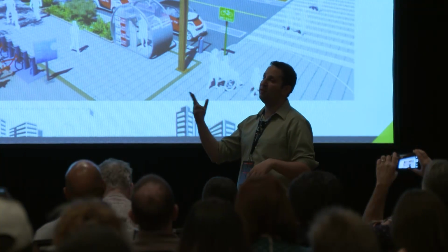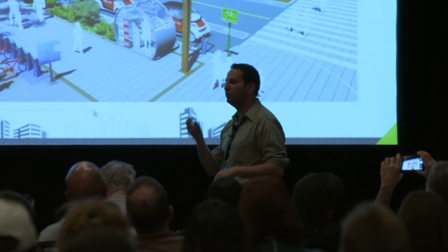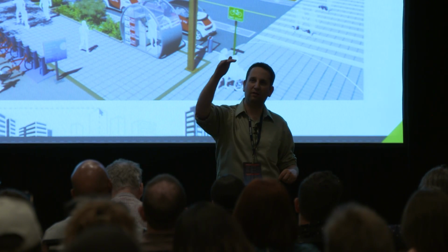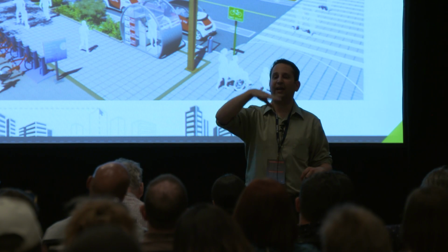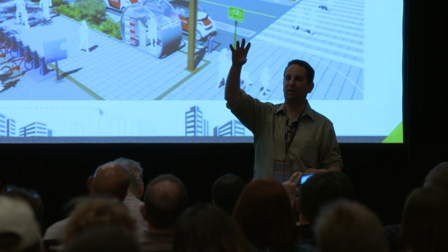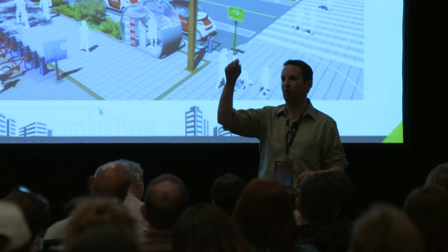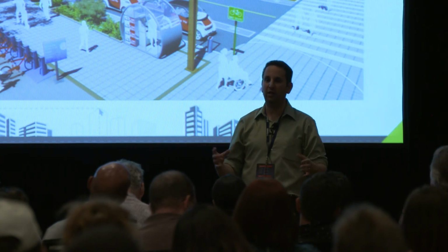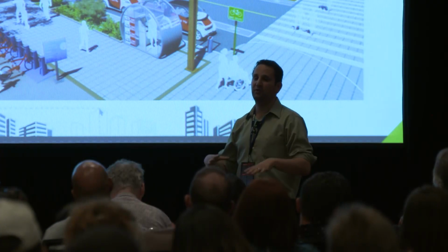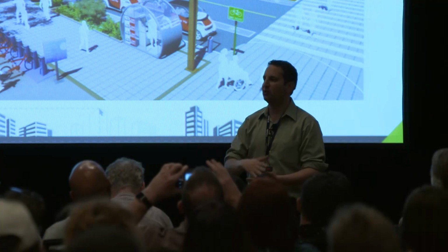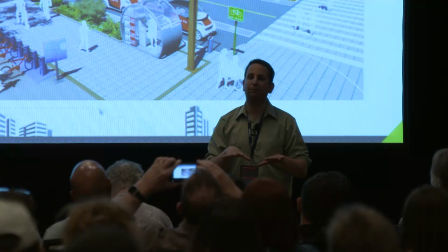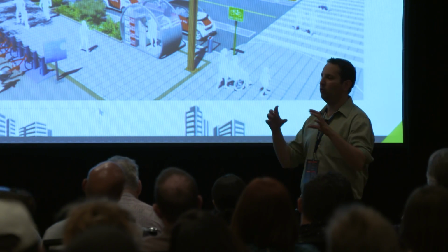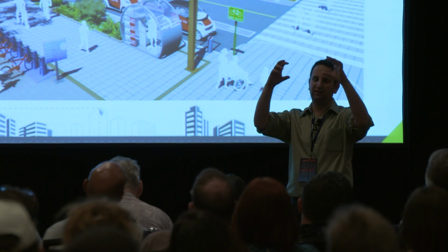The other thing that affects performance and file size is the amount of geometry that you have in your model. That's under Window, Model Info, Statistics. I dream in this, by the way. I see menus, I'm just kidding. Window, Model Info, Statistics, Show Nested Components. It will tell you how big your file size is in terms of geometry. SketchUp can handle a lot of geometry. What they don't tell you with every release is that they're actually ripping out the hood and improving the performance. So for example, when I used SketchUp in 2003, it could only handle a file size with 50,000 faces.